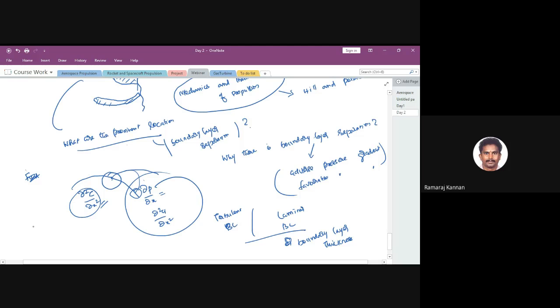What is the critical Reynolds number for laminar to turbulent transition, for a flat plate, for a circular cylinder, for boundary layer separation, the critical Reynolds number for those things and all? Just check it up with that. How does the boundary layer profile go from laminar to turbulent? Fully, what do you mean by fully developed flow?